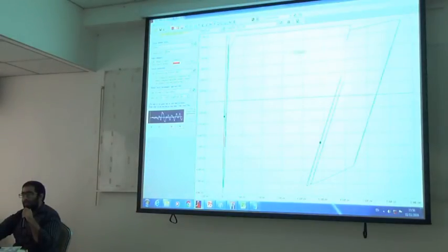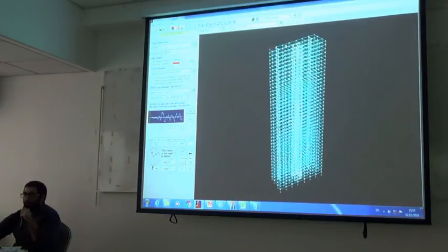So you can see that the behavior is something like this. The loops will look very strange to you, but actually, if you see the deformation number over here, the rotation in this hinge is very small. You might think that the loop is very big, but the rotation in the hinge is very small, because if you see the rotation number over here, it looks so small, right?